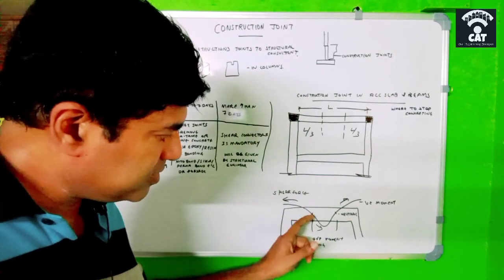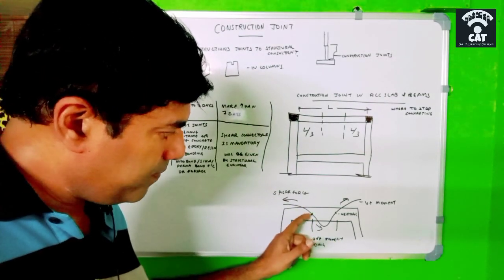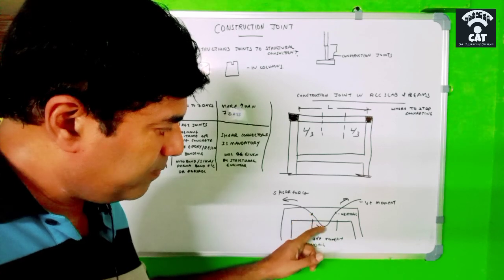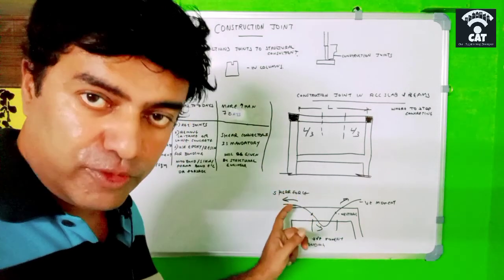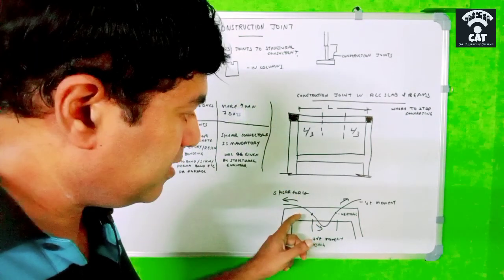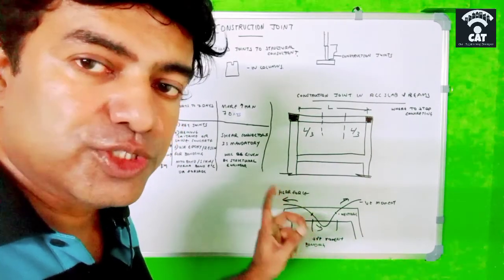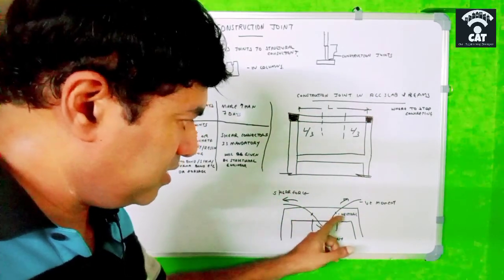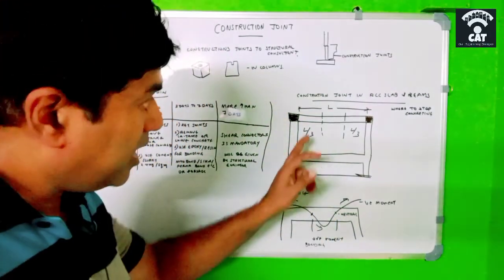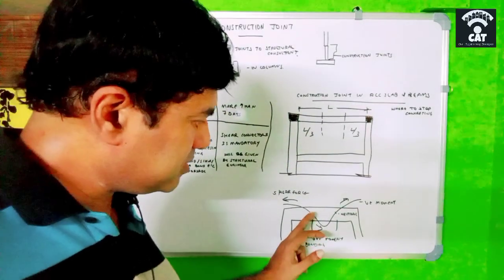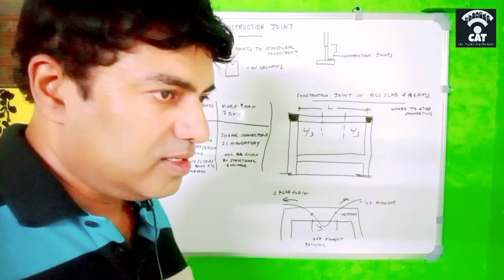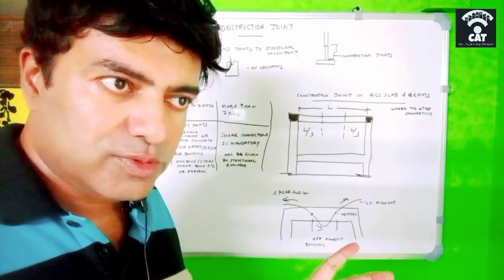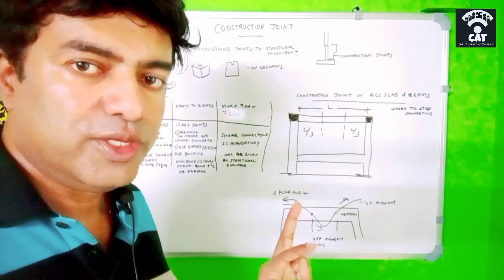And you know, this is the area in the slab where the bending moment is changing, and the force is 0 at this neutral point, at this point and this point. That means L by 3. The point L by 3 is the area where the bending moment changes sign and the moment will be 0, it will be neutral.